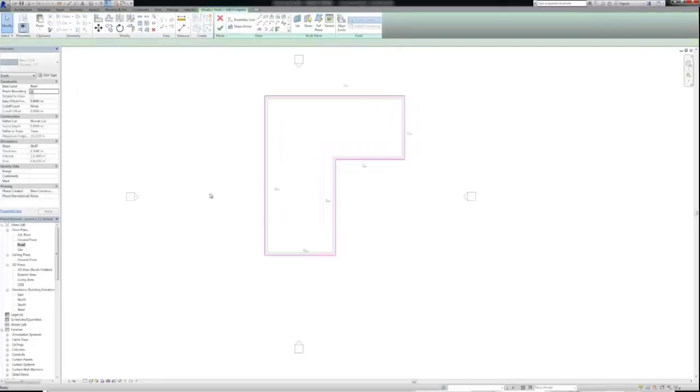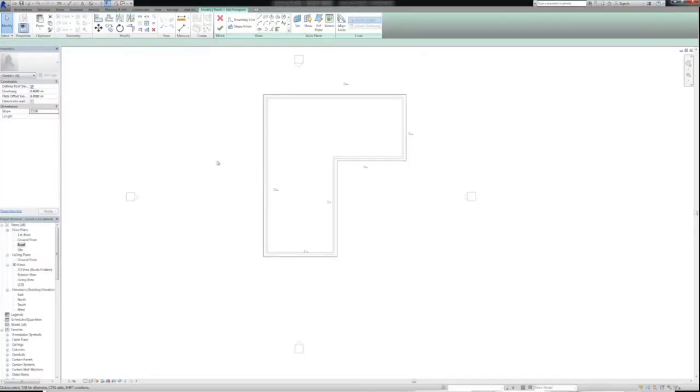After selecting the roof, we can make simple changes by editing the footprint. When selecting a line, notice that we can change the overhang and the angle. When selecting multiple lines, we can edit these properties at the same time. Let's increase the overhang so it's 400 centimeters and make the slope of the roof 25 degrees. Click the green check mark to see the changes.